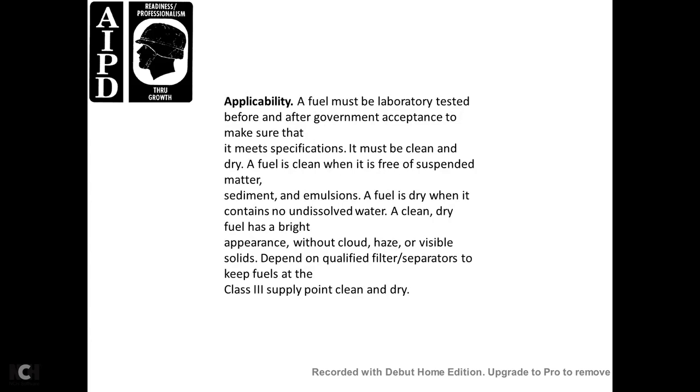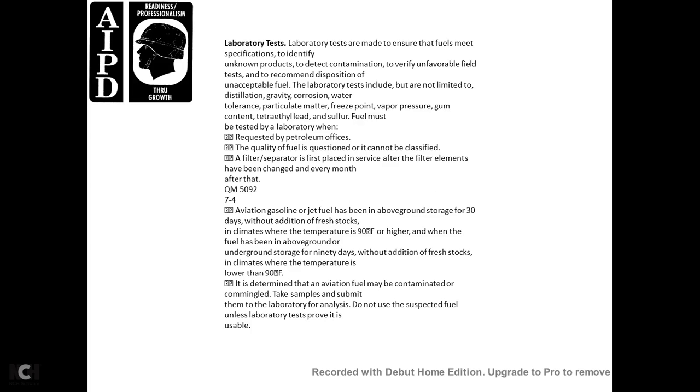Applicability. Fuel must be laboratory tested before government acceptance to make sure it meets specification. The fuel must be clean, free of suspended matter, sediment, and emulsion. It must be dry, containing no undissolved water, and bright in appearance, without cloud or haze or visible solids. Depending on quality, apply filters and separators to keep the Class 3 supply point clean and dry.